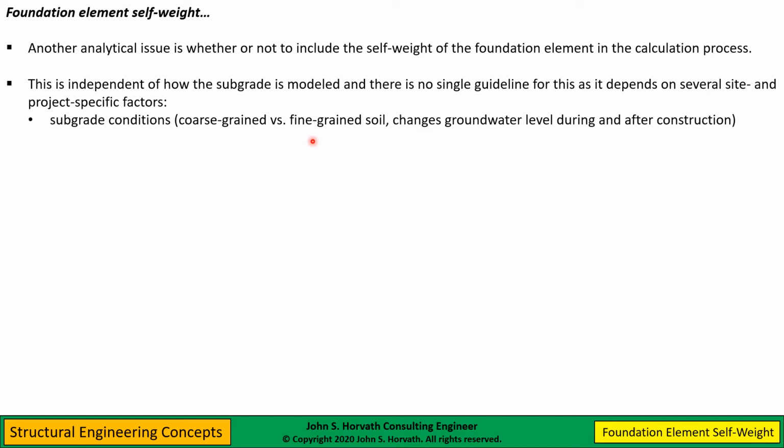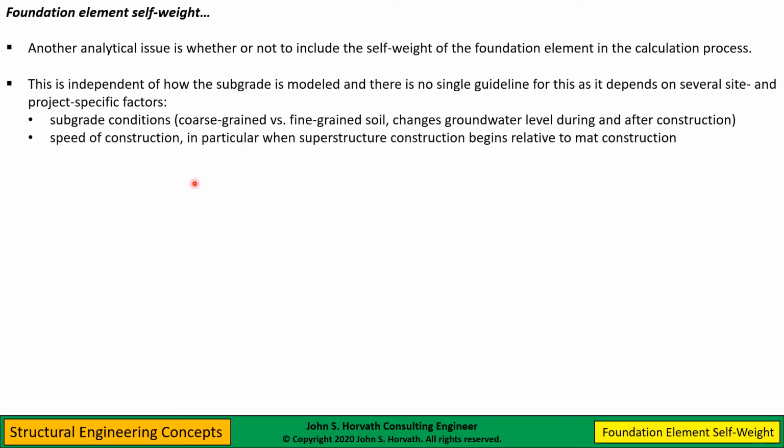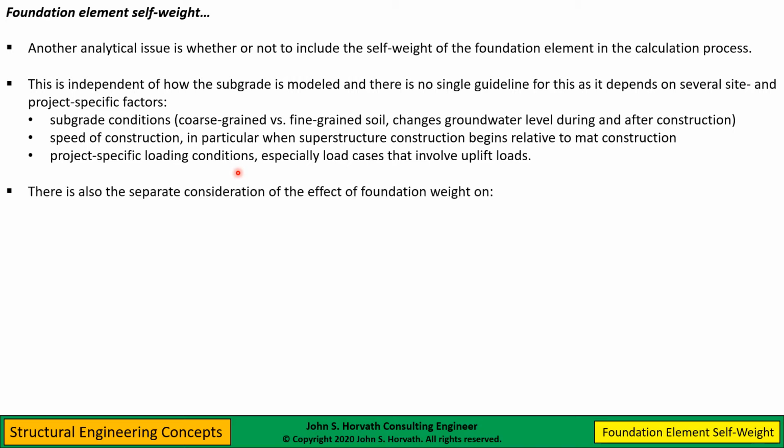I'll show you some case histories later on where this was a factor. The speed of construction, when do you build a superstructure relative to the mat? How long does it take for the mat concrete to cure? Things like that. And also loading conditions, especially when there's uplift loads from usually water pressure, but nowadays it might even be wind loads as well, or seismic loading.